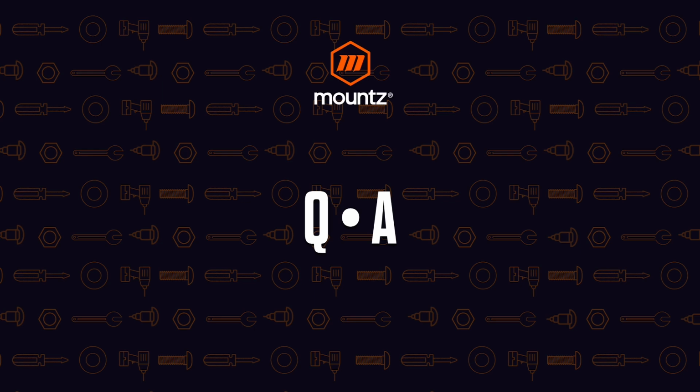What's the difference between the torque verification and torque validation process? So this gives you the ability to actually test your tool in between calibration cycles. So you don't get the notification of a tool that's come back from calibration that was out of tolerance when it was found at the calibration testing. And so the validation and verification process allows you to make sure that the tool is still operating within its limits before it goes out for calibration during the time that it's being used. So you're monitoring that tool, understanding how that tool is performing in between calibration cycles. So you notice that if a tool is coming out of its specification, that tool can either be looked at, recalibrated, or adjusted.